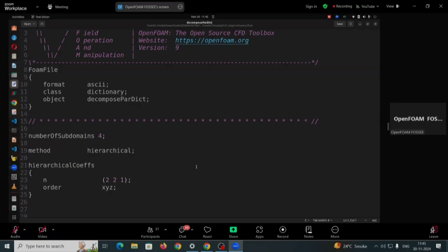Okay. So if in each subdomain there are only a few cells, then that takes away the advantage of having multiple cores. So you need to balance. What I mean by that is that the gain in speed, or the reduction in computational cost, is not linear with the increase in the number of subdomains. So maybe you need to try that for your separate case, right?